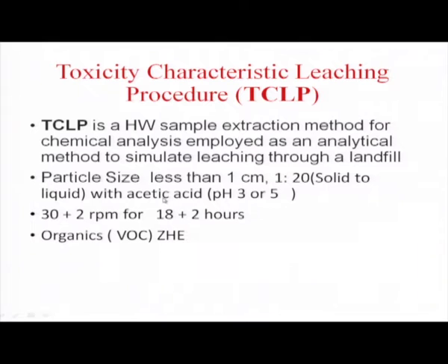The purpose of using acetic acid is to simulate the leaching actually happening in the landfill, because any organic materials there will be slowly converted, and one of the important products is acetic acid. So, that is likely to react with the heavy metal bearing substances and likely to leach out. So, that is why acetic acid is taken as the testing fluid or leaching agent to conduct this test.